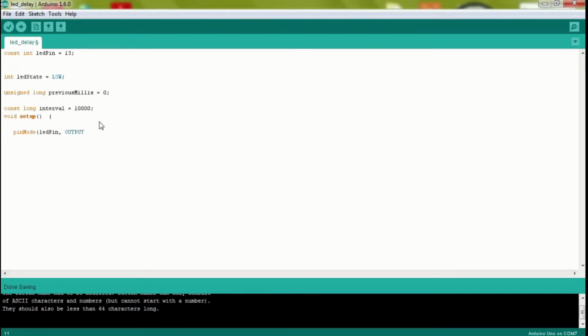We're going to initiate pins as outputs. This is usually commanded by pin mode in the void setup, which makes certain pins on the board outputs or inputs depending on the program. Make sure you end every line with a semicolon. The loop is going to turn the LED high, or on, wait, then turn it low, or off. Then repeat forever as long as it is on.